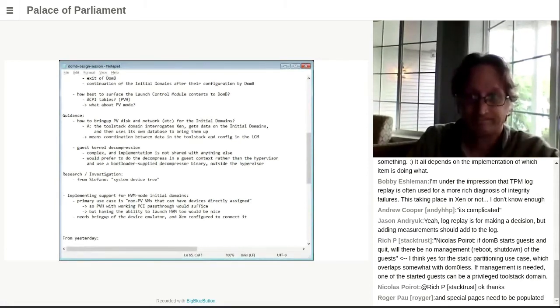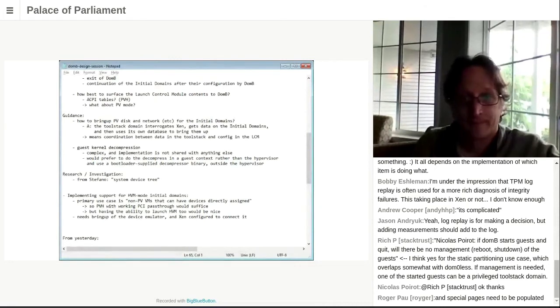So in that case, your tooling becomes the bootloader, and your actual guest configuration is the bootloader config. For us, the way it worked is we're using U-Boot, right? U-Boot is our bootloader. U-Boot doesn't quite have the equivalent of a grub.conf, so there isn't really a grub.conf with stanzas and config under each. So basically, it was down to doing some device tree editing and some loading. So it was a bit more difficult than writing grub, not that writing grub is trivial, right? But it's certainly safe to say it's harder to write. It was really not possible to do it by hand. I mean, you could do it by hand, but you will get it wrong. I will get it wrong 1 in 4 or 5 times, costing me hours to debug.